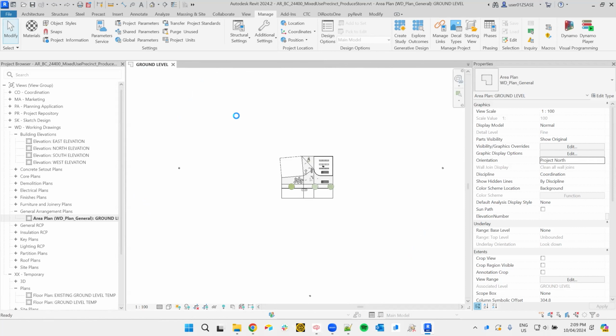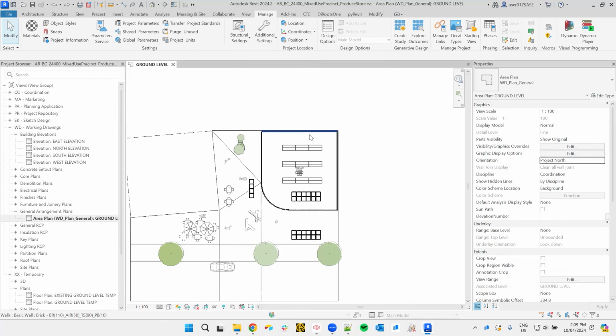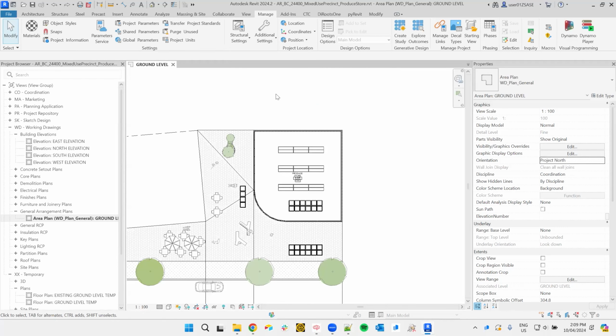And we're doing acquire coordinates mostly because of the issues surrounding publishing coordinates back to models where others own elements in workshared files. So this is just a little bit more of a robust method, but you can publish coordinates if you're more familiar with that process. Okay, now that we've brought that in, let's have a look at the link manager and some of the settings surrounding that. So the link manager allows us to manage all of the links within our project.